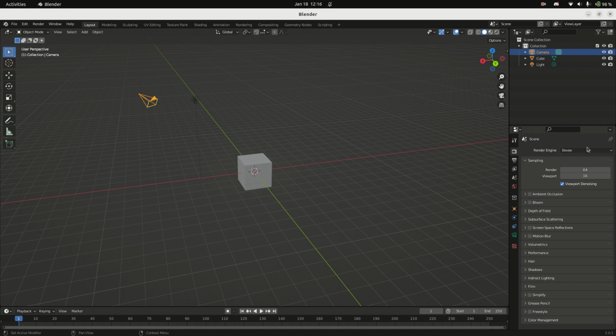So Blender comes with, at least this version came with 3 different rendering engines. Eevee is its default. Workbench is some other one that they've included, and Cycles is like an older version. Now, the cool thing about Eevee is that generally their renders are much nicer looking with the Eevee engine. However, Cycles has a lot more additional features that might be useful while building your models and texturing them and animating them. Particularly, I will use Cycles mostly when I'm creating assets for a game that I'm working on. But for now, I'm leaving it on Eevee.